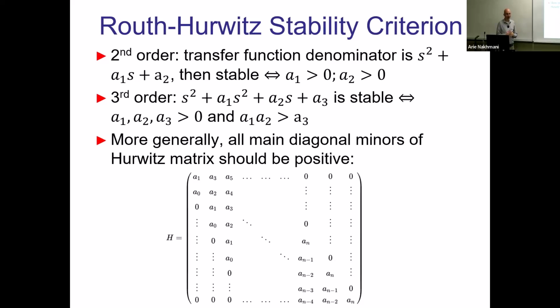But if you want to go and develop more criteria of that kind instead of all of these tables and so on, you have a very interesting determinant here of that type of matrix. So the matrix is going like that. Coefficients are every second coefficient. You just write that as a line: a1, a3, a5, and so on, until you have the last coefficient, and then you complete that with zeros, whatever number of zeros you need.